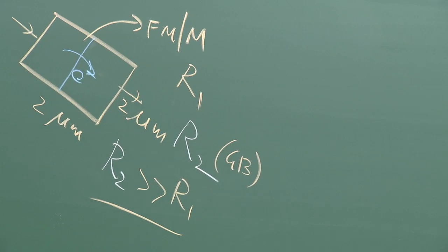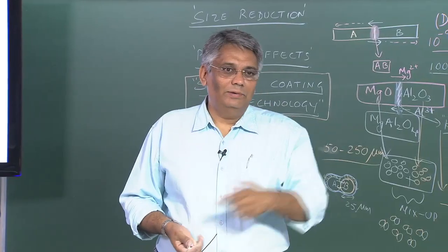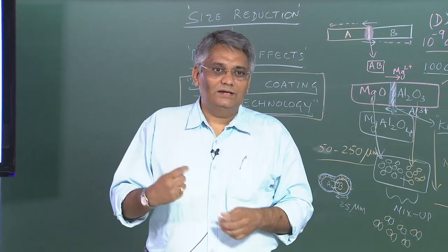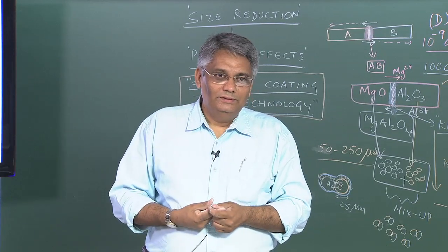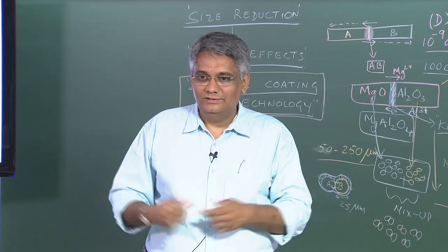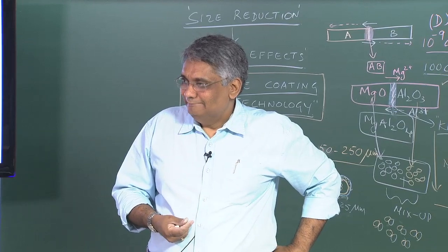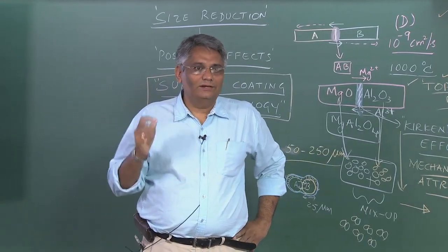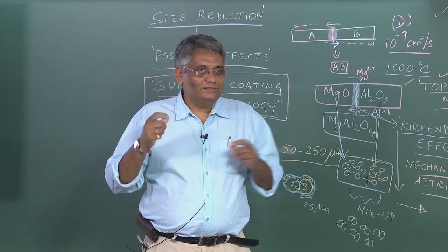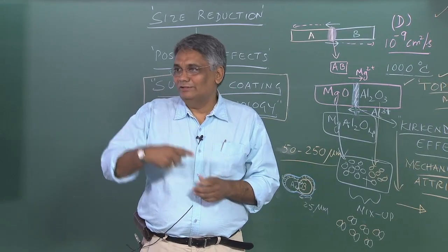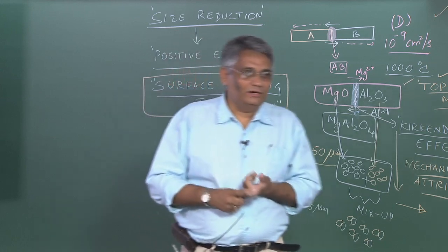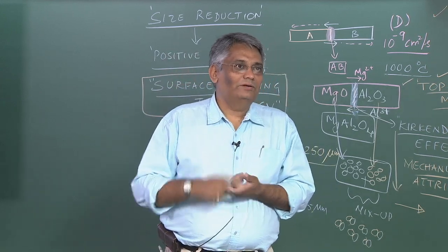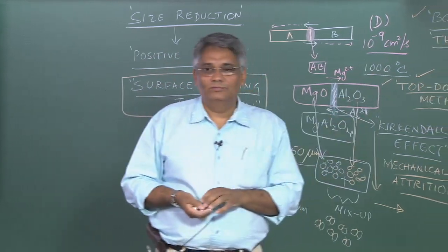By creating this grain boundary, you have created a tunnel barrier. When charge carriers tunnel through this barrier, they experience an additional resistance that's called a tunnel resistance, right? Of course, the tunnel resistance arises only when the electrons tunnel through. For the electrons to tunnel across this barrier, the barrier width has to be of the order of 10 to 15 angstroms.